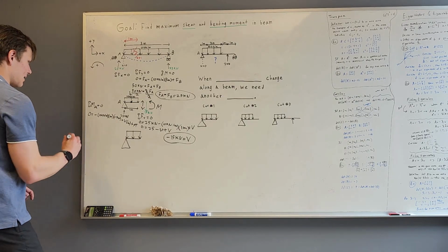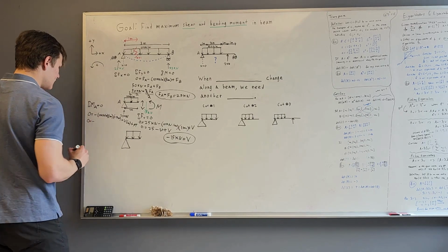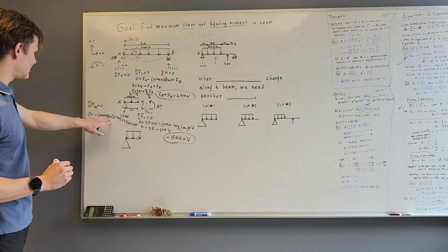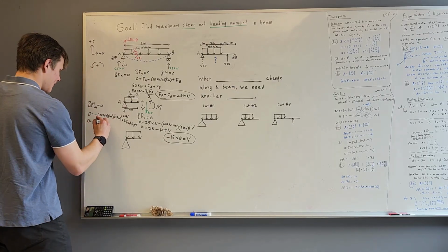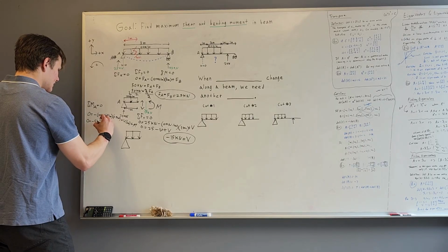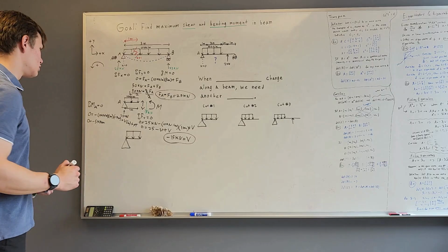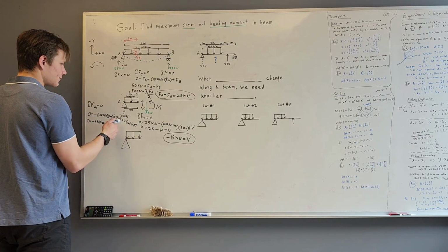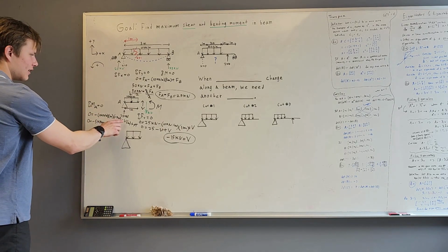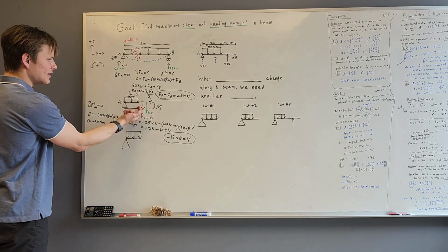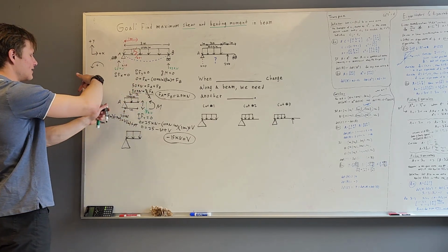So then let's just try to clean this up a little bit. We'll get 0 is equal to negative 10 kilonewtons per meter times 1 meter, that's 10 kilonewtons, times 0.5, so half of 10, negative 5 kilonewton meters, plus our shear, which is negative 15. Because remember, I took V as positive because I'm using our original assumption that V is pointing up, which creates that counterclockwise moment.